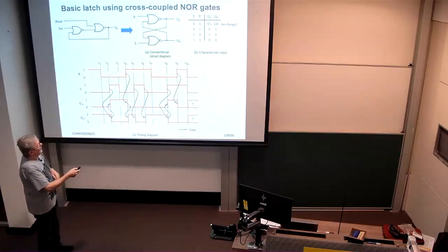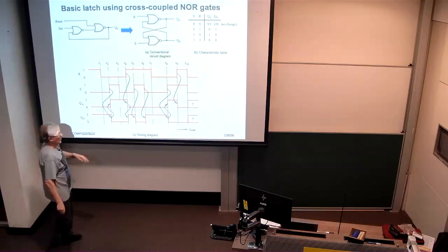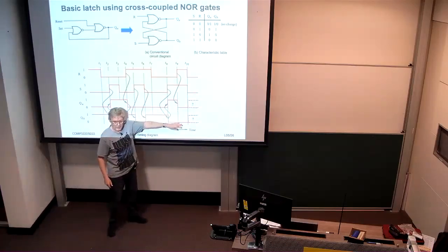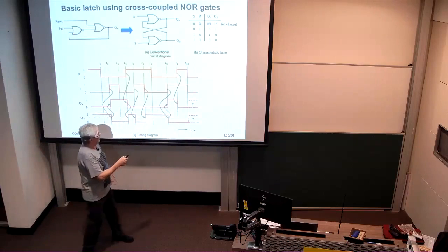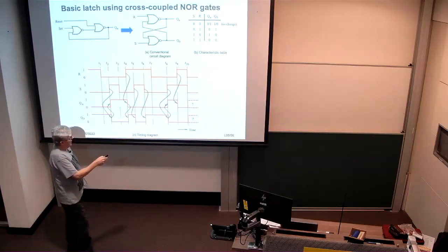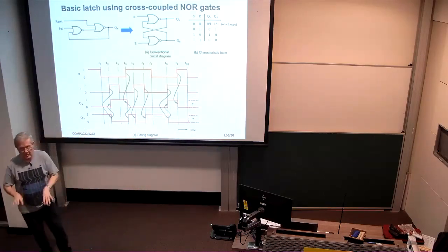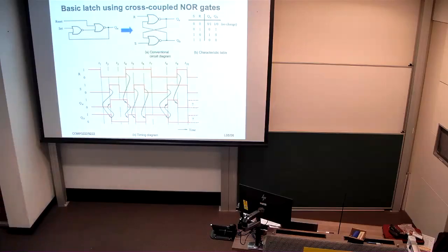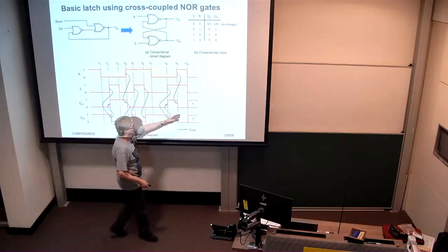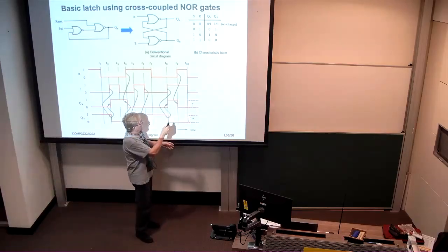Now right at the very end here, we see that both R and S are asserted, and therefore QA and QB are low in this interval here. And let's say that both R and S are deasserted simultaneously. Well, what happens then? What should the next state be of QA and QB if from the state where R and S are both high they go to low?